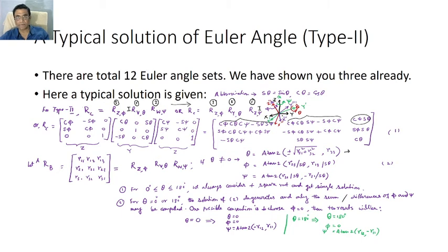So this is my coordinate frame xyz, and then about z first, so I am looking from here, about z by an angle psi, and it flipped from x1 y1 to this position. Then with respect to y, looking from here, in the positive direction with respect to me, angle theta is rotated. The coordinate axes are flipped and take the position like this.